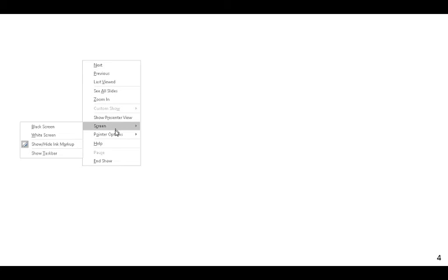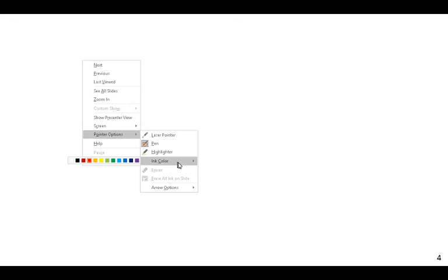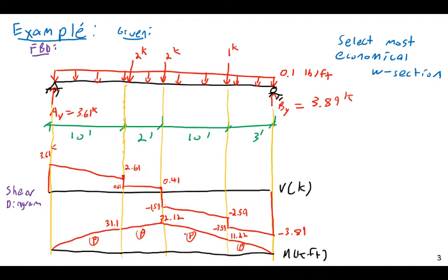So we said that we wanted to design based on max moment. What that means is that we want to design for moment at the outermost fiber. In other words, we're going to need to design for this 32.2 maximum moment. So let's see how we can actually do that. The issue is that we need to design for the moment at the outermost fiber, but we don't actually know the depth of the beam, do we? So we'll need to see how to work this.